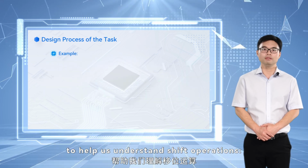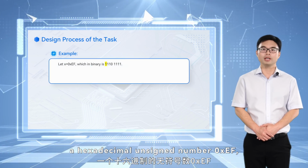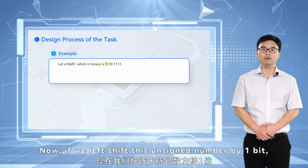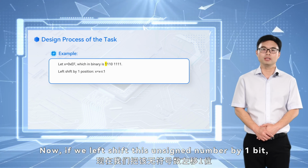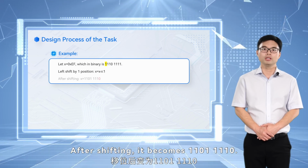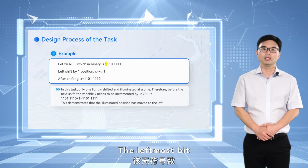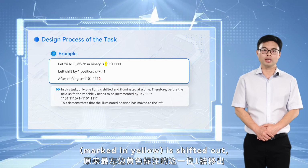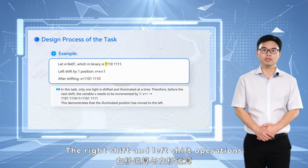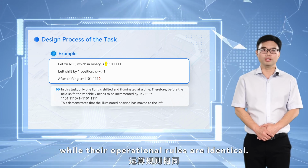Let's look at an example to help us understand shift operations. A hexadecimal unsigned number 0xEF in binary form is 1110 1111. Now, if we left shift this unsigned number by 1 bit, the operation format is x shifted left by 1 bit. After shifting, it becomes 1101 1110. The leftmost bit, marked in yellow, is shifted out, and a 0 is added at the rightmost position, marked in red. The right shift and left shift operations only differ in direction, while their operational rules are identical.